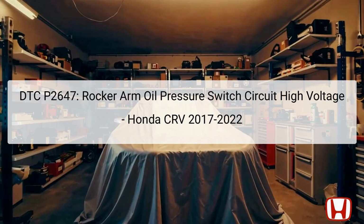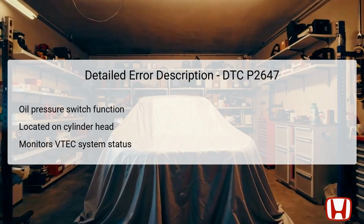and increased emissions. The rocker arm oil pressure switch is designed to monitor the oil pressure within the engine's VTEC system. It plays a crucial role by informing the powertrain control module, PCM, when to activate or deactivate variable valve timing, thus optimizing engine efficiency. The switch is typically located on the cylinder head, where it can accurately gauge the oil pressure levels.